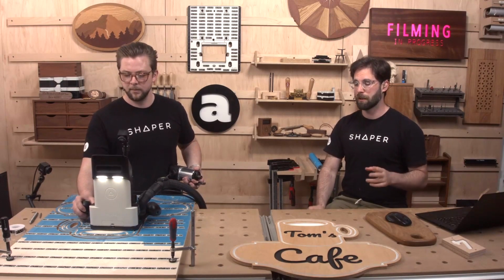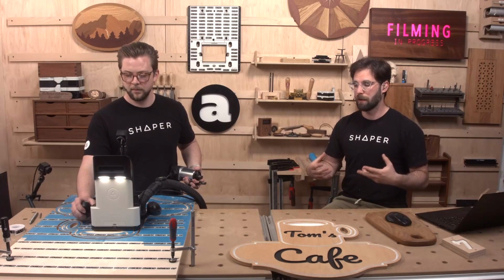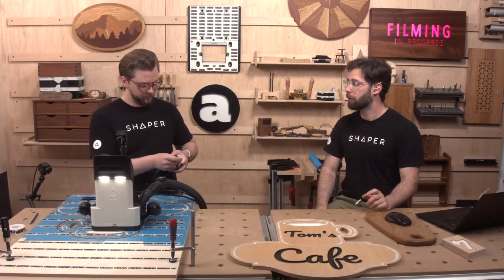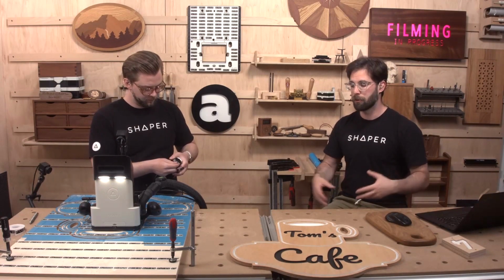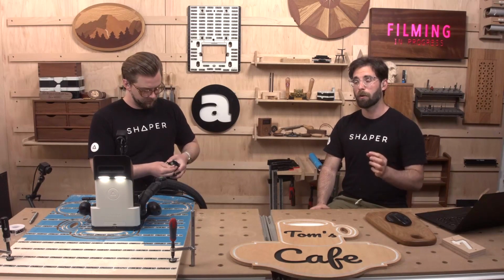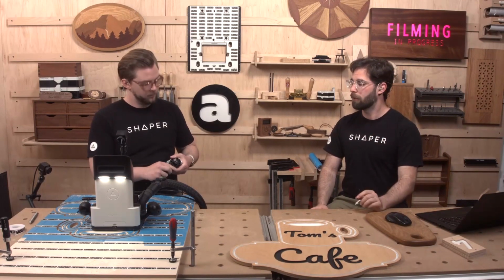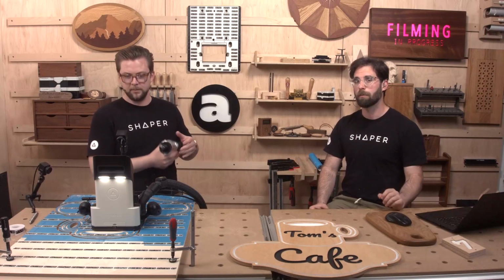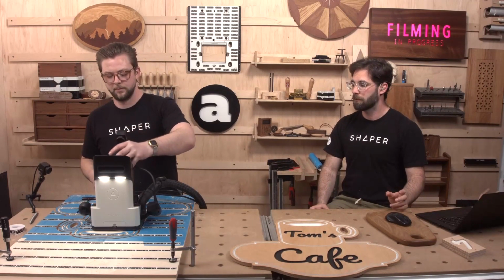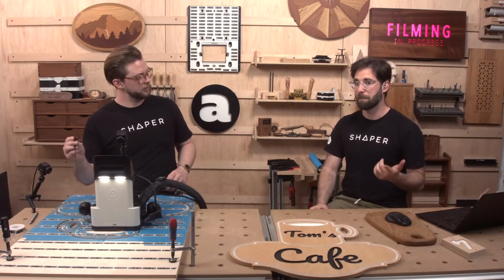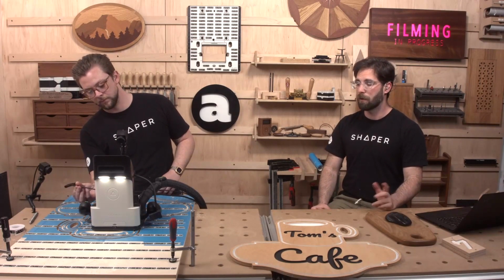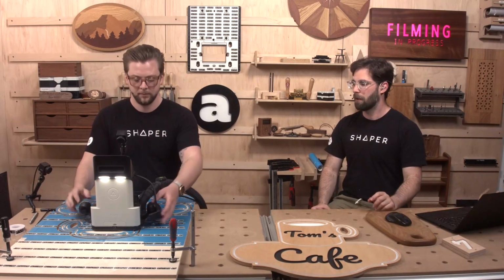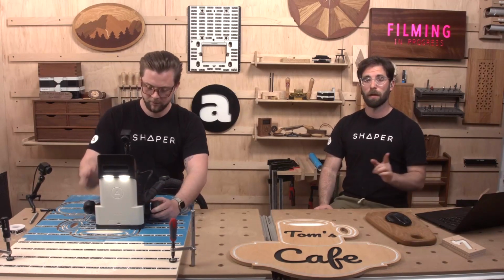1/8 inch is important because the less material you're removing, the less you have to push against it. So I really like the 1/8 inch much better than a 1/4 inch for working with metals because you're pushing less material away. And then by 1/4 inch, which means that's a 1/4 inch cutting length, it gives you much more stiffness. So you'll notice actually in harder materials like brass and aluminum, soft metals, that the stiffness of the router bit has a big impact on the quality of your cuts. And so I really like the 1/4 inch length, which is stubbier than our standard 1/8 inch router bits. But it really, really, really helps. So that's one to keep in mind.